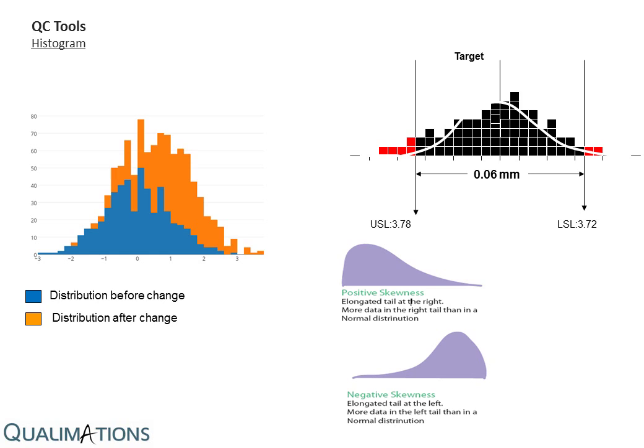The histogram is normal if the highest frequency is in the central group and there is symmetrical tapering on either side of the central group. The natural or normal distribution would indicate that the process being studied is under control. A histogram with an unnatural pattern may indicate that there is possibly something unusual with the process, but is not evidence of a process being out of control.